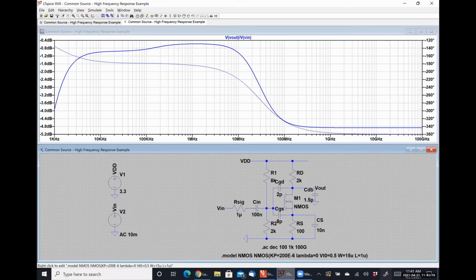But we have a low pass response, meaning what we're looking at is from effectively right here and on. So we have that roll off at a pole frequency of here about, I think it's 16 megahertz or so. And then this is how the phase behaves. If you give me just a minute, I'll throw one up that's our speed.